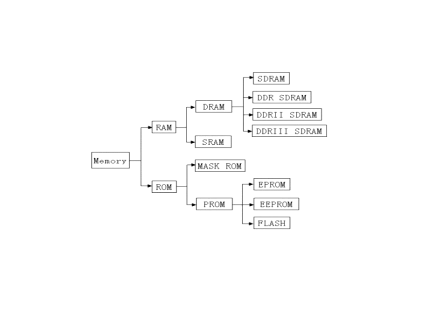Here's your family layout of these different kinds of chips. All memory is RAM or ROM. And here's the different kinds of ROM that we've been talking about here. And over here, mask ROM is the same as ROM. Okay, RAM has different kinds of RAM. These are all volatile memory, and these are all non-volatile memory. These are difficult to write into. These are not.